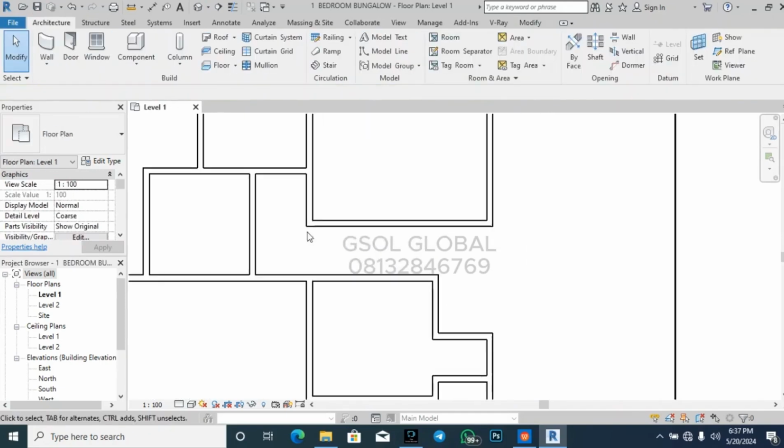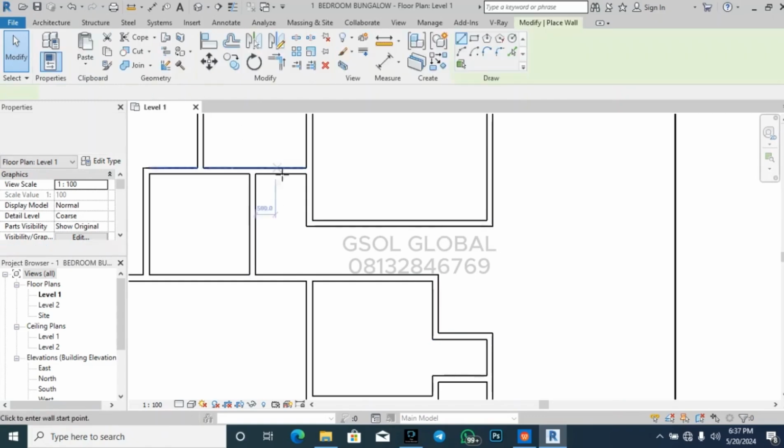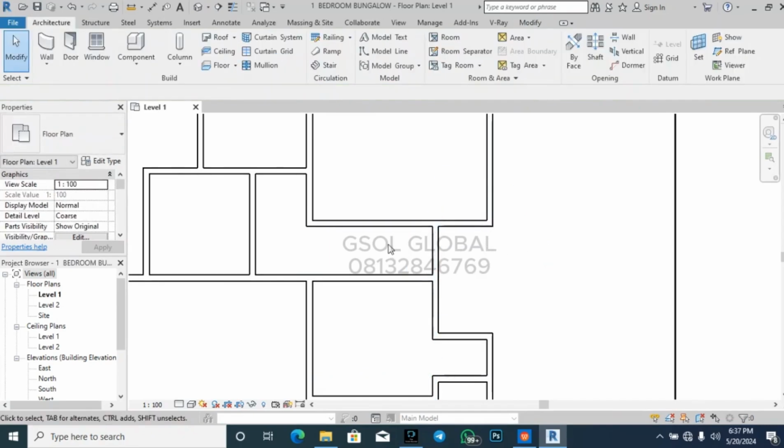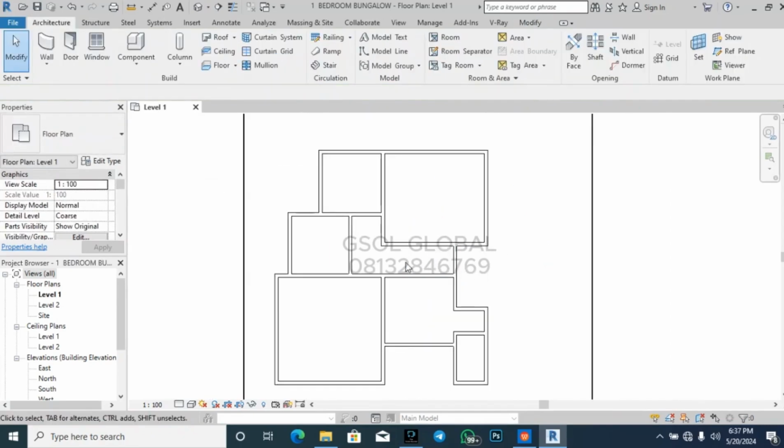So remember this particular lobby here, it's just looking as if here is an exit. No, we have to cover it. So I don't have to put anything here any longer because I want ventilation to come from this place inside. So I'll put my wall here. In that wall, I'll be having a window in that place. All right, so remember you have to watch it step by step. Don't be in a hurry. This is plan design. You have to watch it step by step.